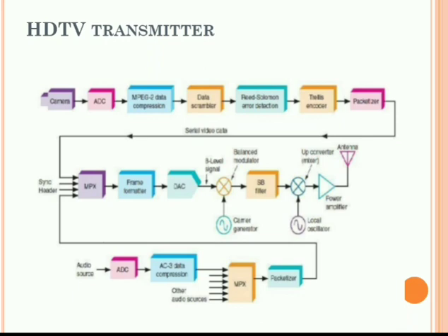Okay, what we have seen now: the packetizer output is multiplexed along with some synchronization signal. Means whatever the data streams for the audio and video we are having, that signal and a synchronization signal, these three things are multiplexed at the same time to form the signal to be transmitted. Whatever the actual signal that we have to transmit, for the purpose of forming it we are using multiplexing here. The result of that is a 188-byte packet containing both video and audio data plus 4 bytes of synchronization bytes.